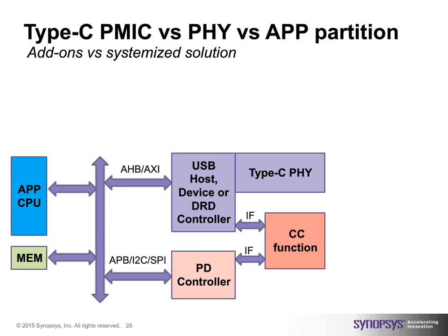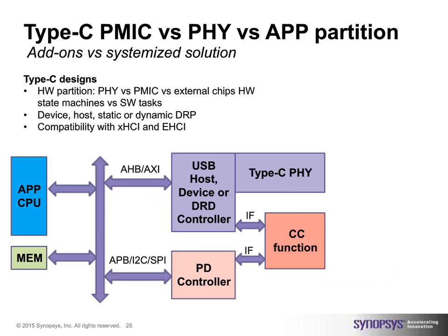That opens up a lot of questions. So do you put things in the PHY or the PMIC or external chips? Do you have hardware state machines? Do you have software tasks to do this? Do you have a CPU there at all? If you're going to do a product, is it device or host? Is it a static dual role port so that it's a device today and a host tomorrow? Or is it dynamic like on the go? And what about software compatibility with the existing host software stacks?